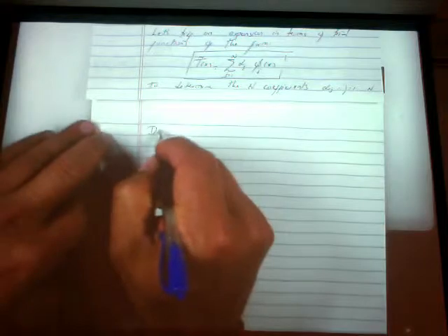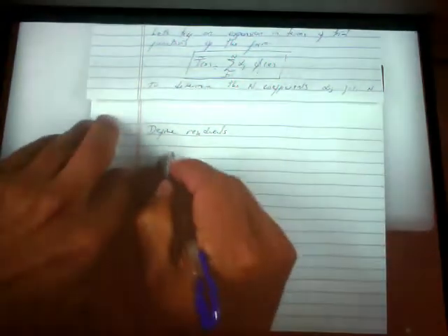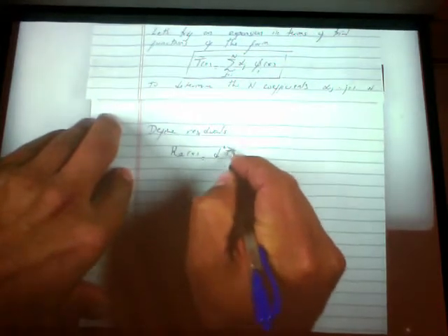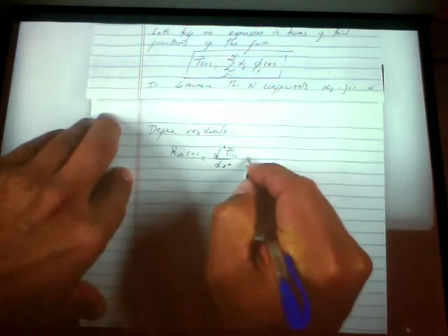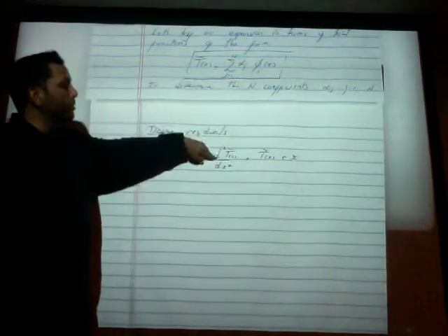So what do we do? Define the residuals. And that would be, well, the residual over the domain is equal to the second derivative of this expansion plus this expansion plus x. Right? Because that is the governing equation. And should this be the exact solution, this residual will automatically go to 0. But we're presuming that we don't know the exact solution.